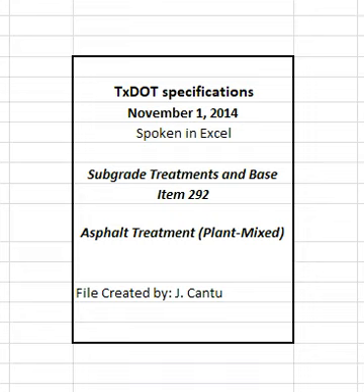Immediately take appropriate corrective action if surface irregularities, including but not limited to segregation, rutting, raveling, flushing, fat spots, mat slippage, color, texture, roller marks, tears, gouges, or streaks, are detected. Continue placement for no more than 1 day of production while appropriate action is taken. If no appropriate corrective action is taken or if the problem still exists after 1 day, suspend paving until the engineer approves further production.